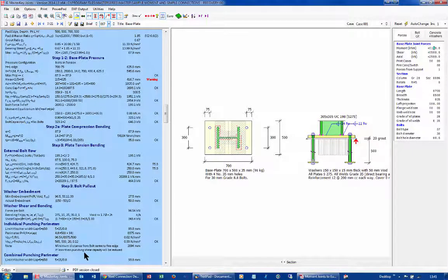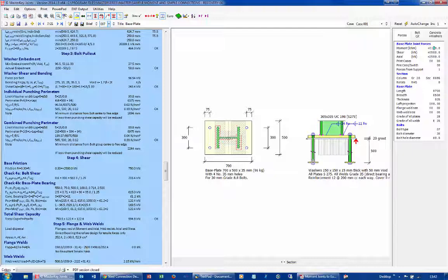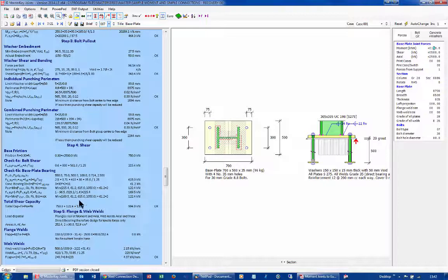Where we come into some more EuroCode playing around is in the shear. Obviously the friction is very similar, the bolt shear capacity is very similar. The plate bearing is again assuming your bearing capacity on FCD min. Now the interesting thing here is that we must use the weaker of the grout and the concrete strengths, whereas previously up above we were actually allowed to use the stronger of the two, provided the grout was within a certain zone. And also here, because this is a horizontal bearing, we're not allowed to use that enhancement either. So we've got a detrimental effect on our bearing capacity of our bolts. So yes, bolt bearing has failed, has been reduced the capacity. The welds are very similar to previous with no real changes.